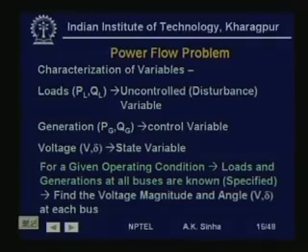If we see the real power or the reactive power, the equality is that the sum of all the real power generation or reactive power generation is equal to the real power load plus the losses. Now, how do we know the losses beforehand? We can know the losses only after we get to know the voltage at all the bus bars. Then we can know the power flow in each line, and then we can calculate the losses. So, we do not know the losses, and therefore, we cannot specify all the generation. This is one of the major problems of power flow analysis, but we can always handle this.